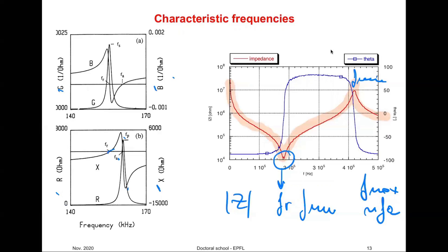You like operation at resonance frequency, either resonance or anti-resonance frequency, depending on your application. For example, if you work at resonance frequency, you would like the impedance to be as close as possible to the impedance of the instrument that you are using this piezoelectric material with. That internal impedance is usually 50 ohms, so you would like this to be as close to 50 ohms as possible.